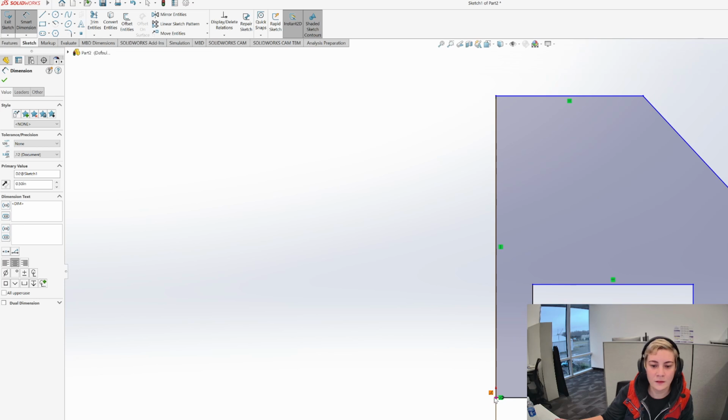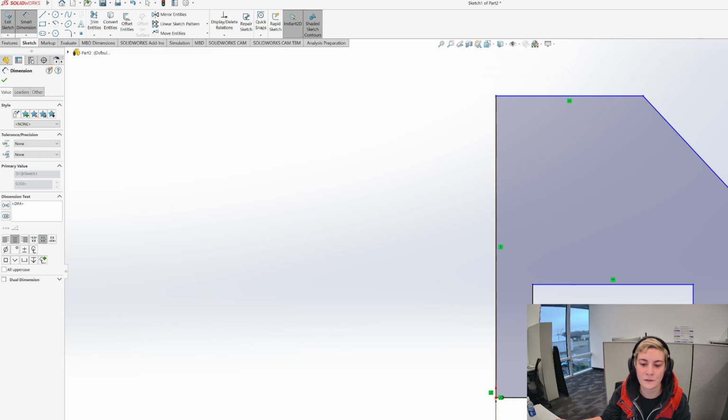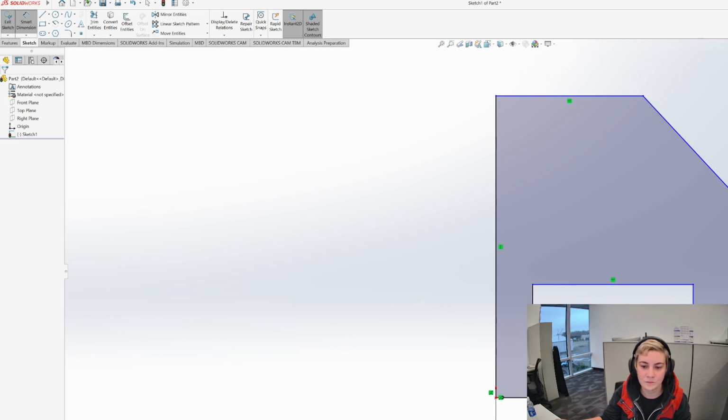You're going to have to click the point you want to dimension, and then you have to click again to release the number, to drop the dimension number where you want it, basically. So like this 0, I had to click a second time to put that 0 there. So this is going to be 1.